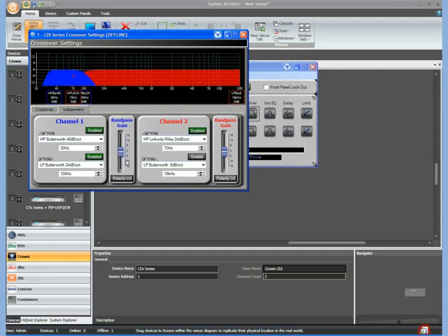On channel 2, I'm going to set a basic 100 Hertz, 24 dB per octave, which matches this 24 dB per octave. I am not going to set any low pass frequency here to roll off the highs, but I might want to, in some cases, roll off extreme highs. In this case I don't, and in most cases you don't need to. Again, I can adjust the relative output between these two bands. Generally you don't need to, but occasionally it'd be helpful.